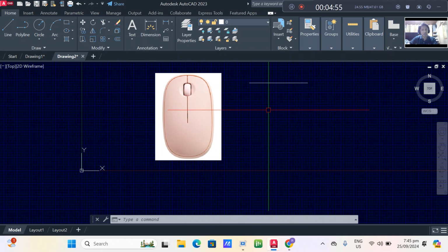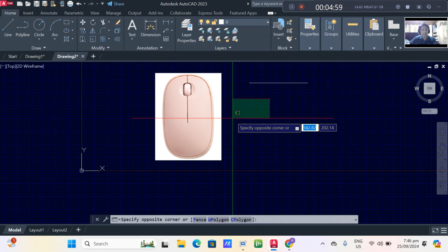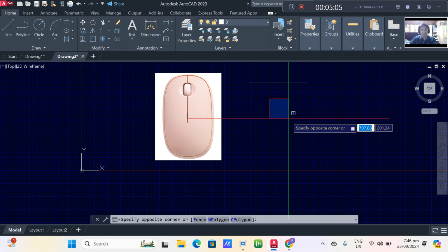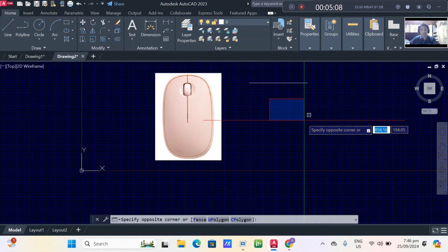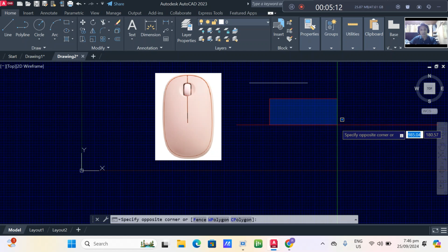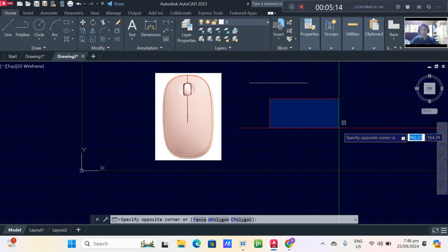You have to practice left click, release, then drag to the left for a green rectangular fence, or left click, release, and drag to the right for the rectangular blue fence.